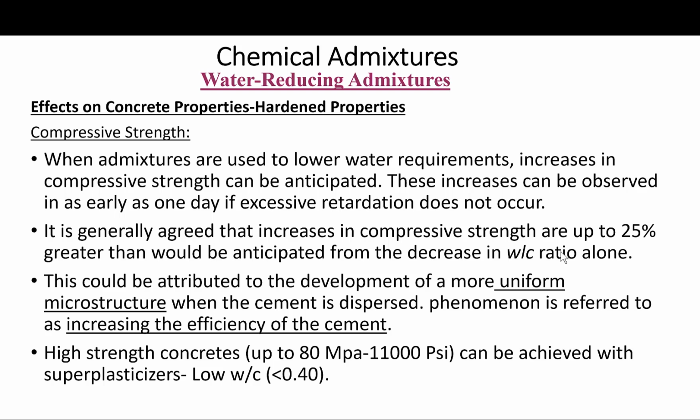So the low water cement ratio also improves the rate of strength gain at early ages and can be very useful in the precast concrete industry. After 24 hours of normal curing, it is possible to obtain compressive strength that takes 8 days to develop using a higher water cement ratio, such as 0.5, for example. Even larger gains are realized, of course, if a steam cure is used.